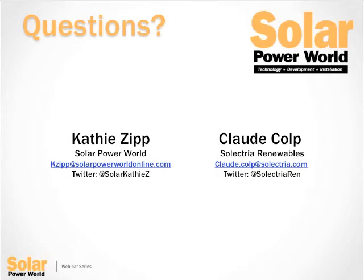However, we are working on developing a smaller version of a rapid shutdown box for the residential line. Now, the residential line, the TLs, and even the three-phase TLs have arc fault detection circuitry built into them. So they don't need that component, but it's not feasible to mount them in such a location to comply with rapid shutdown. So the need for this rapid shutdown combiner box, or basically rapid shutdown string level disconnect box, is being developed.